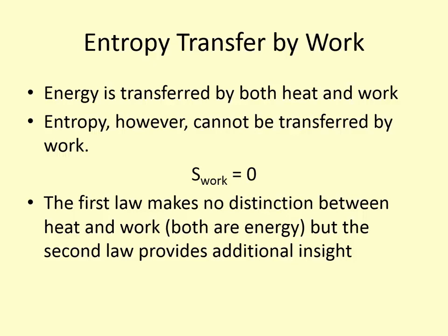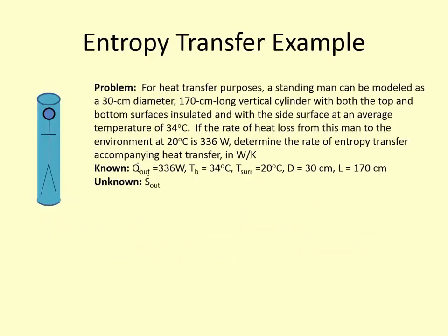Okay, so the second law tells us that heat and work are not the same thing, they're different. Although they may balance numerically, you have to know what direction, what quality this energy source is in, in order to determine if a process can really happen. And if a process occurs in the direction of decreasing entropy for the system and the surroundings, then it's not a real process. Although it may satisfy the first law, it wouldn't satisfy the second law.